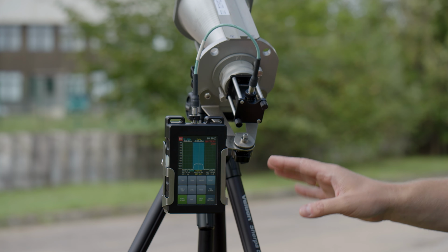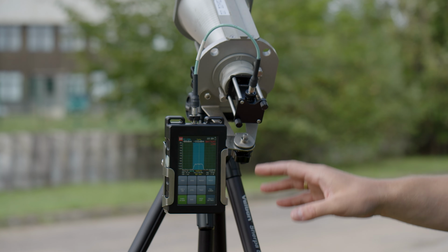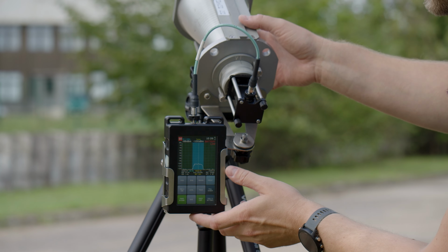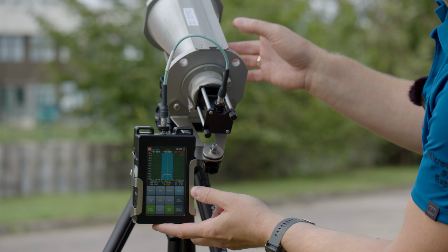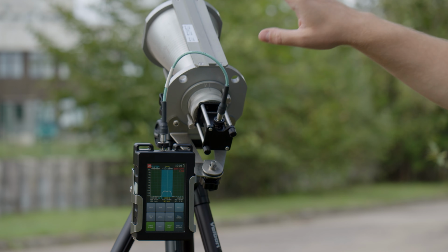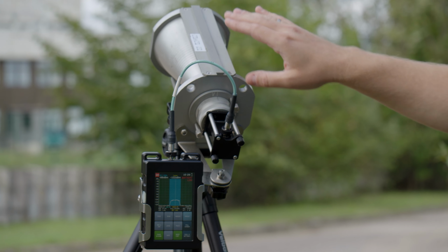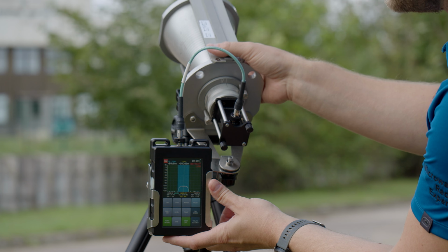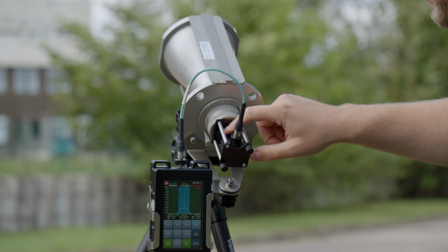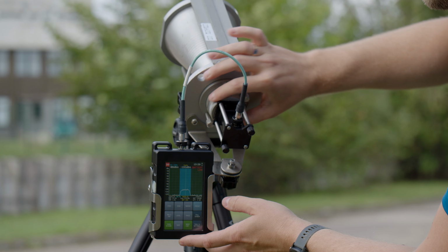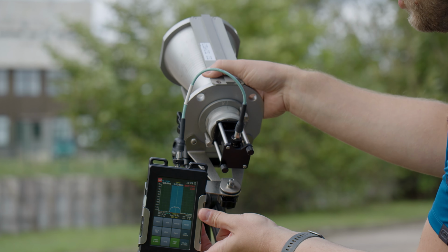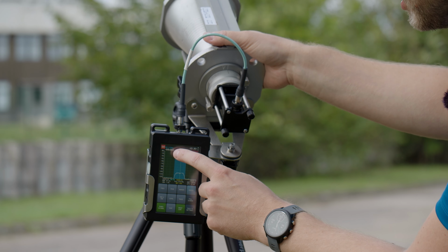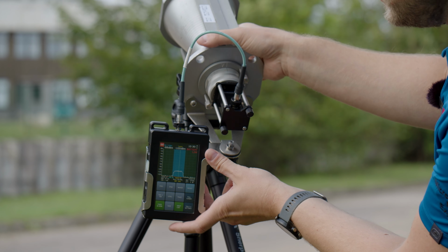Once we have done the channel bandwidth measurements and measured the center frequency of the channel, we can also check the polarization of the channel. Currently the antenna is vertically polarized. To change the polarization, we need to either rotate the antenna or the waveguide on the antenna. What we will do here is rotate the antenna. Currently the signal power measurement of this channel is minus 88 dBm.